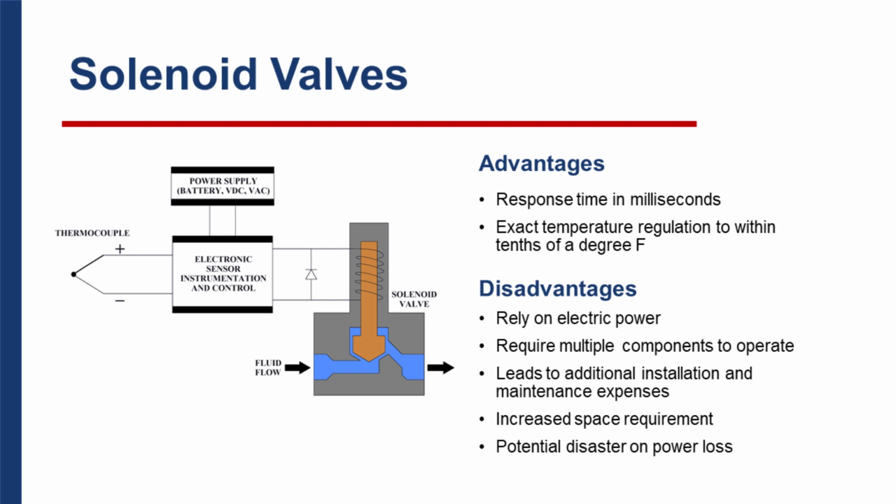So, taking a look at solenoid valves. There are definite advantages to those, and the two most prominent are response time is in milliseconds, so there's no argument there, and also the exact temperature regulation can be done within tenths of a degree.